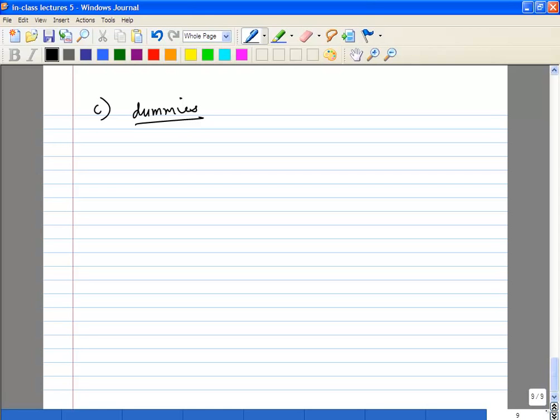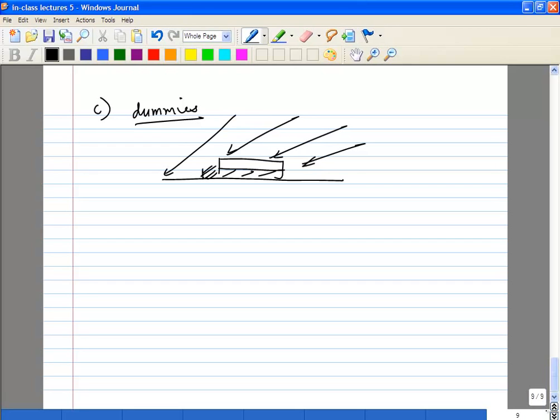So remember, one of the things you have to know is, let's say this was your gate, and you're trying to do the source drain diffusion. This is actually done at an angle of something like 7 degrees from the vertical axis. Which means you actually have something called shadowing.